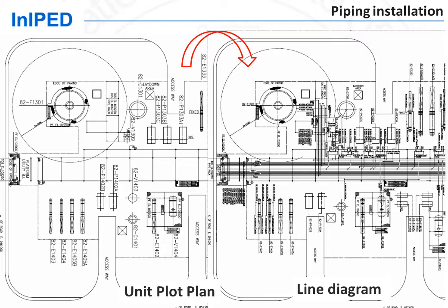As each pipe is shown as one line without taking into account its diameter, these drawings are called line diagrams. They show the density of lines in each area. They also allow to confirm that the unit plot plan is sound, that there are not too many ups and downs on the pipe rack between equipment, and the distances of pipes have been minimized.